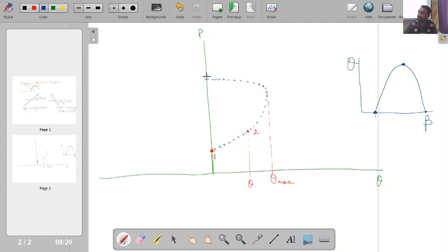Is this point clear? Now if I draw the locus of all these points, I will get a curve. So what I am doing now is drawing the locus of all these points. Are you able to get this type of curve? Okay, so this is nothing but my pressure deflection diagram, which covers the entire range of shock waves, starting from a very weak Mach wave to the normal shock wave.